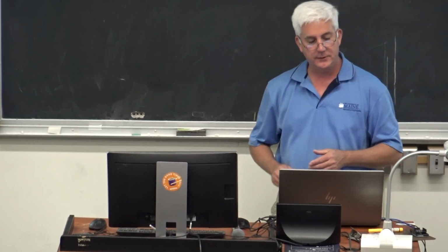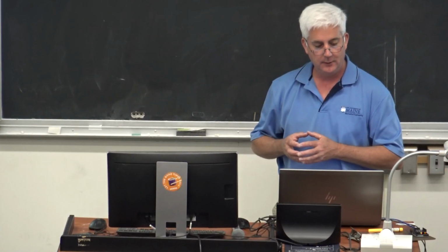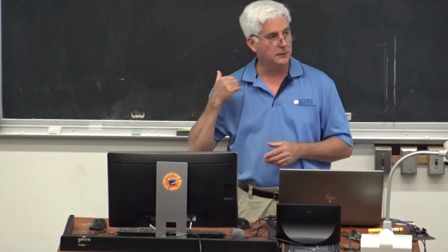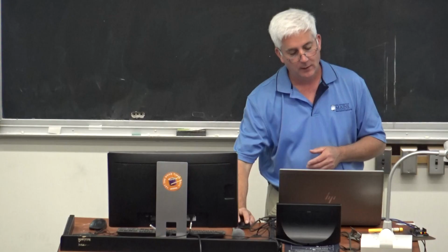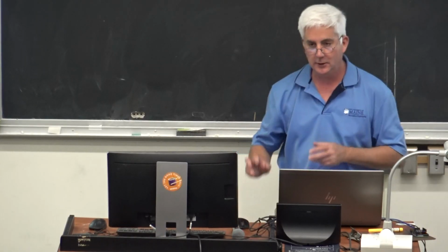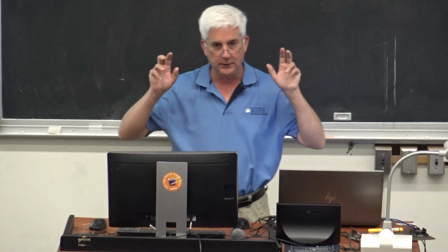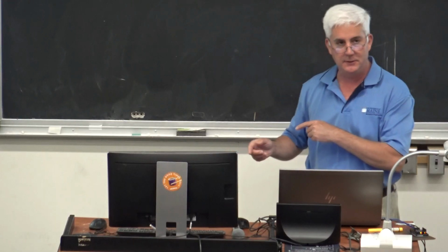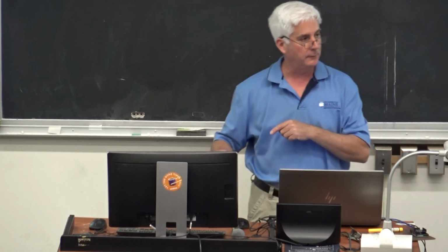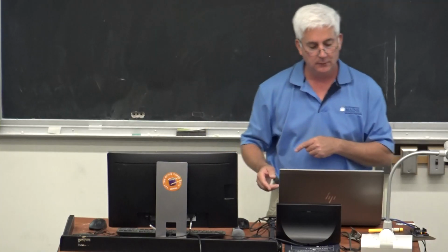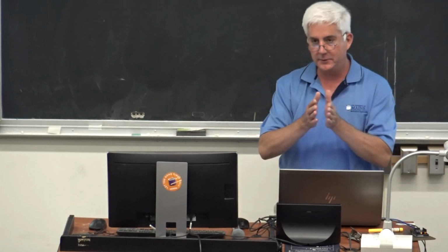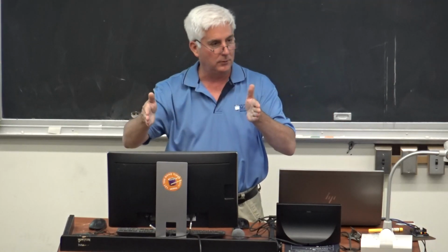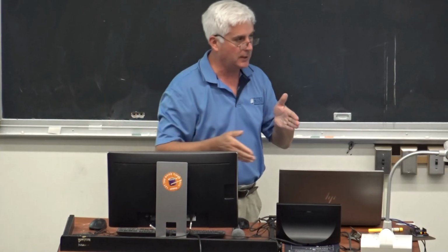So I'm going to then Serial.print the time. So I'm going to send that millis integer stored in time back to the computer. The next thing I'm going to do is print a comma, the literal, a comma. It's in quotes, it just sends a comma. We're going to see how that comes into play when we start sending information back to Data Streamer. So the commas are going to say, whatever value, now jump over one column in Excel. That's what that's doing for you.